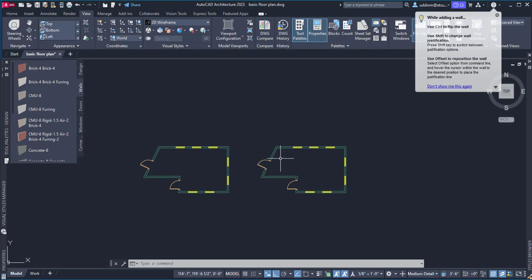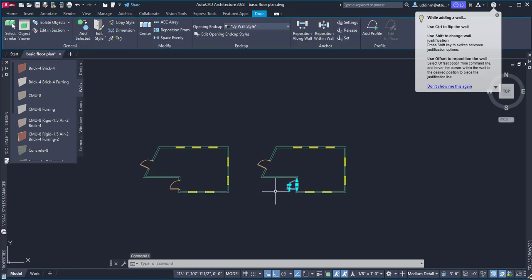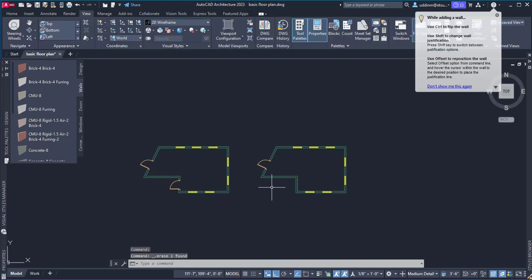But before we do that, one of the things we talked about in a previous video was how to put a roof on a structure. So let's go ahead and put a roof on this structure here. Since this is a top floor, we can put a roof here. The other thing that we might want to do to modify this plan is that if you notice, those doors that were on this first floor plan, they were also copied to the second floor plan. So we don't need this on the second floor, because obviously we won't be entering here. So I can just select that, hit delete, get rid of it. That door, same thing here, delete that door.